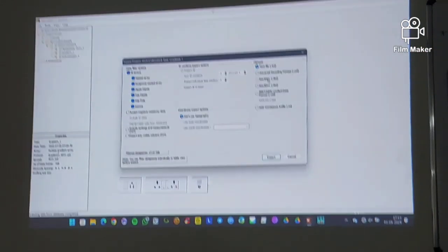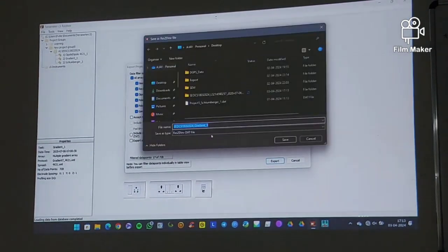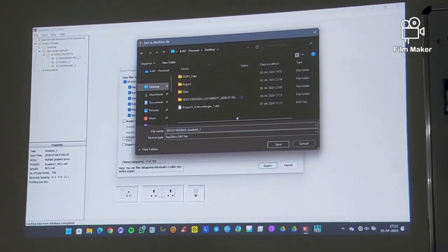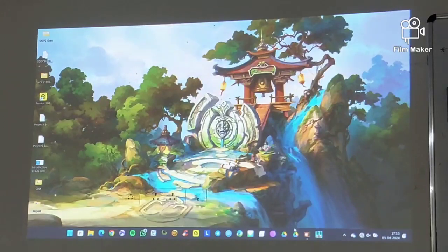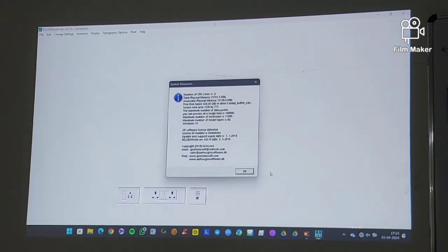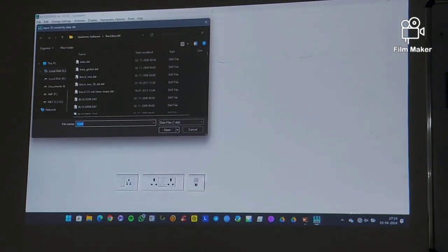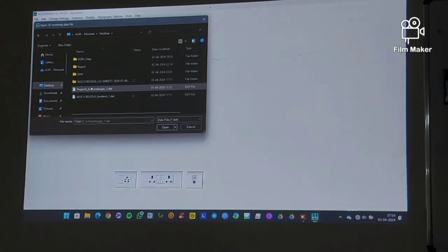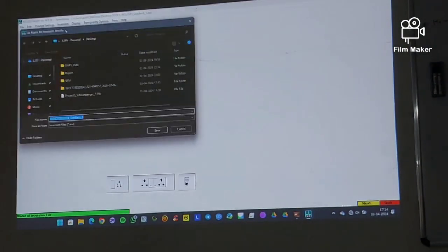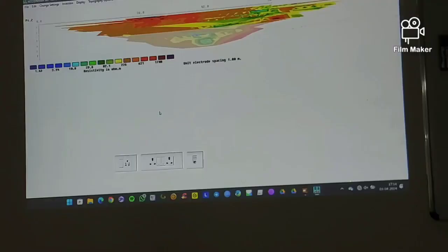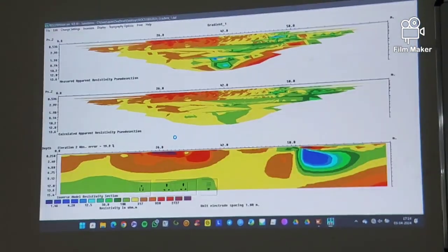Here, after collecting the apparent resistivity data, the data will be put in the software RES2DINV. After putting in the data, we can see the subsurface profile through resolution and contrast, after the inversion process. In this software, an iterative process is used to reduce the error, and it will be set with a low reduced percentage, and it will give a better profile resolution.